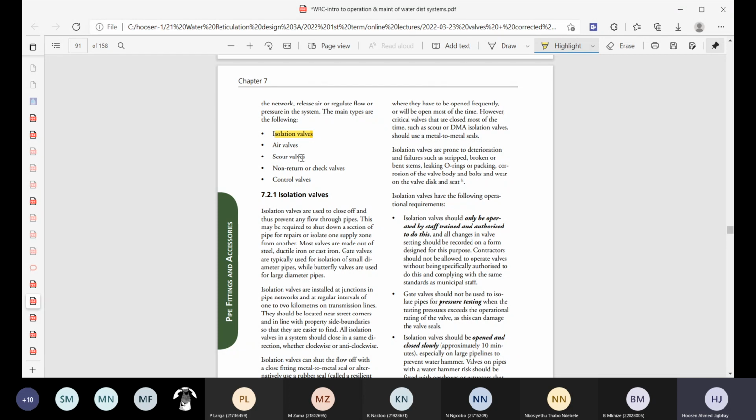The second purpose for scour valves is to remove dirt, grit, sand or gunk, whatever may have accumulated in your pipeline. You don't want sand and things like this appearing in your pipeline because they would cause contamination, and then you have health hazards in that regard.